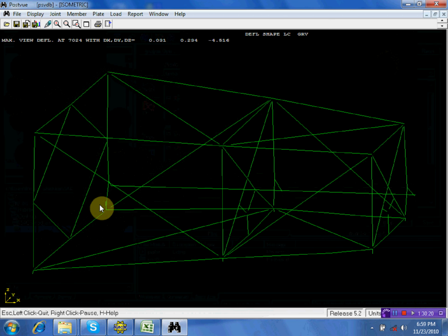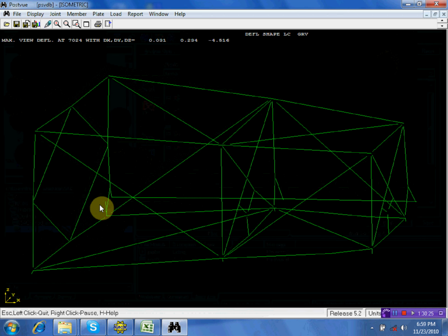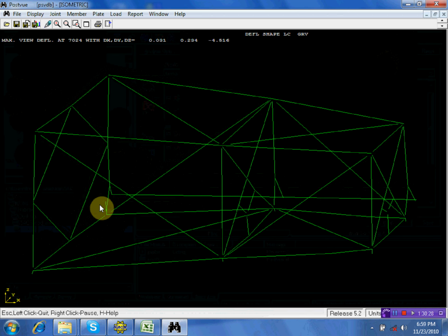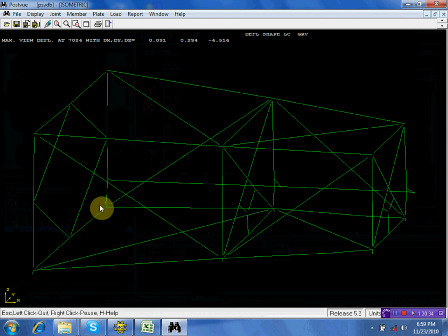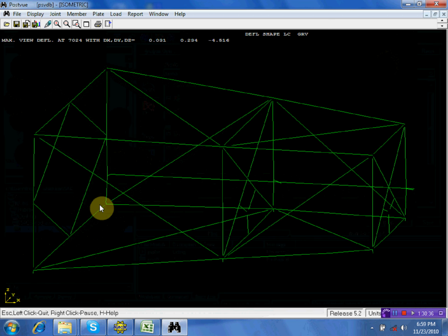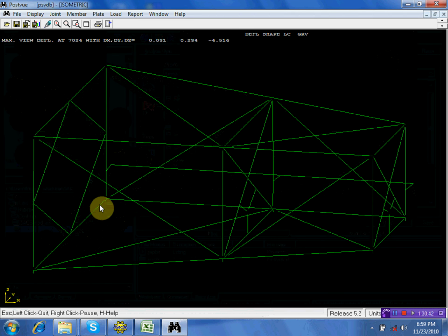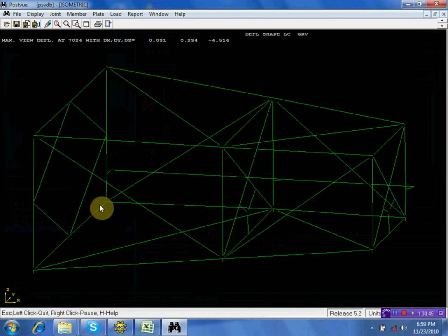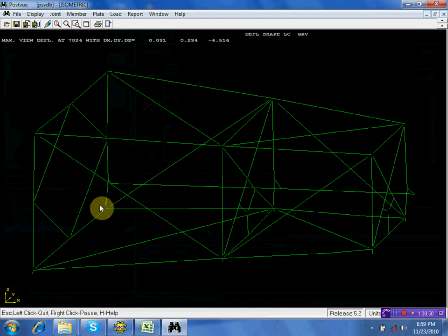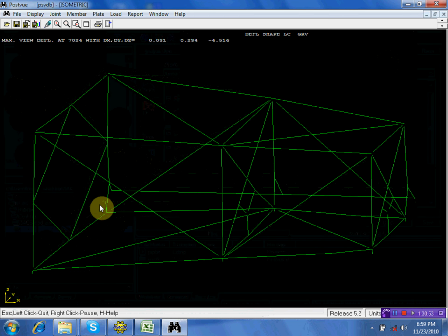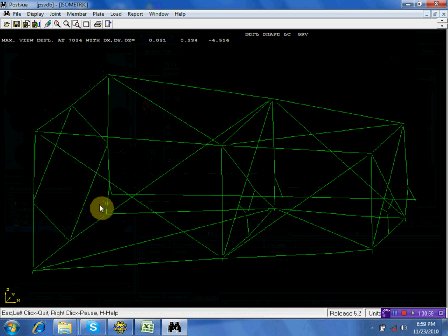We cannot model the cradle. So, for example, skidway, jacket, and then you have the saddle. This is the jacket. Now, we didn't model the saddle. We will not model the saddle. So, what will you do? If this is your jacket and this is your support, all you have to do is not model that and then consider only the jacket hard points. Jacket hard points.